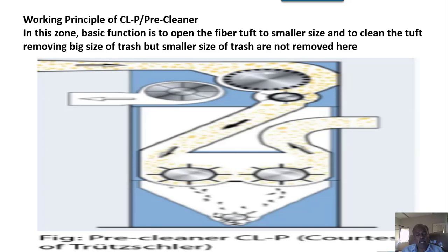Introduction of the cotton will be done in the chamber of this beater. Earlier you have a gripping point, where it grips. If any loose trash is present, it will be dislodged at this place. After gripping and consolidation, and opening to some extent between these two roller lines, the cotton will arrive in this free flight beater chamber.